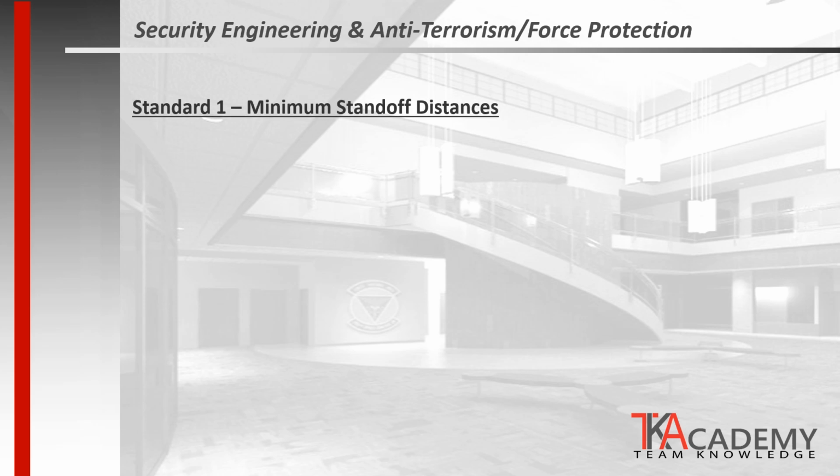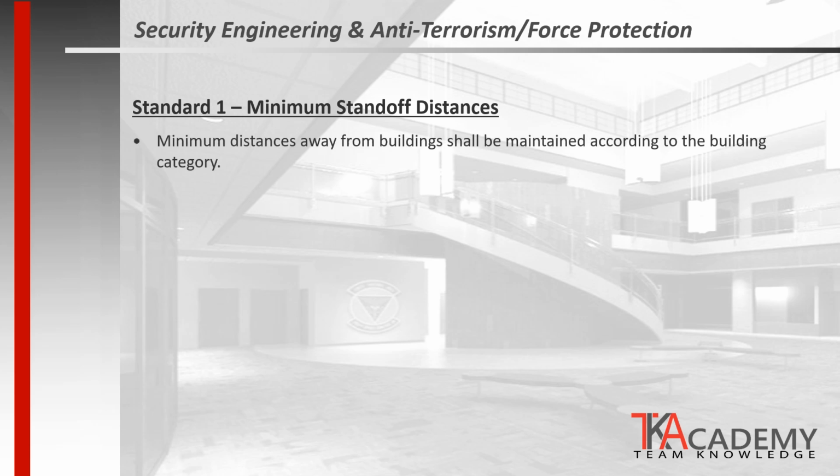The first standard is to maintain minimum standoff distances. This is to protect a building or an asset away from a vehicle threat. The best way to defend is to maintain a safe distance between the threat and the asset. Minimum distances away from buildings shall be maintained according to the building category.